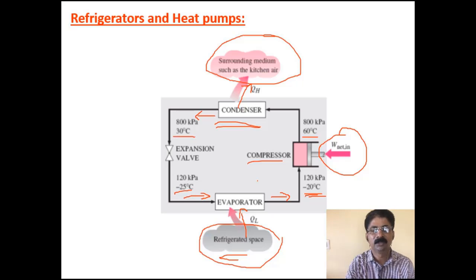Now once again, if you have to pass this to the evaporator coils, just imagine this is at 30 degrees Celsius and your refrigerated space is well below 0 degrees Celsius generally, or very low temperature rather. So if you pass this to the evaporator coils, instead of the working substance absorbing heat from the refrigerated space, the heat will flow from the working substance to the refrigerated space if it is applied at high temperature like 30 degrees Celsius.